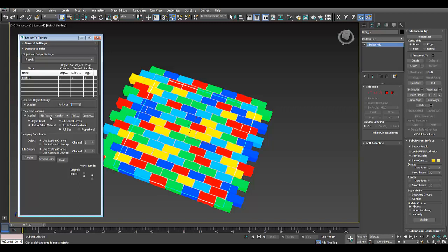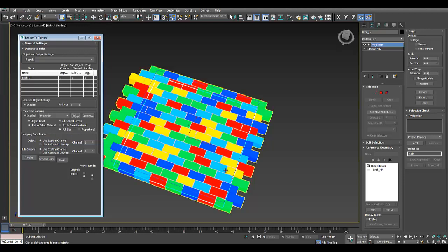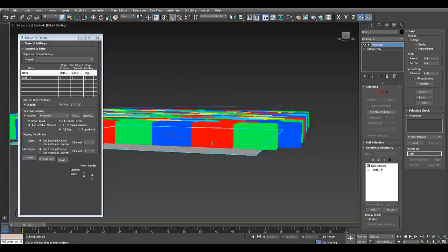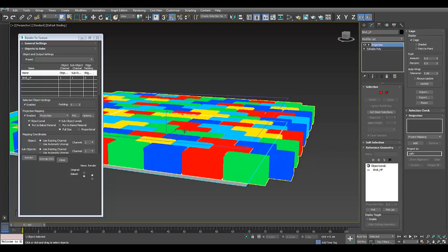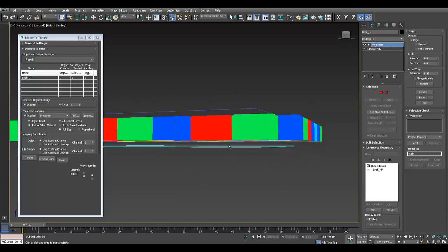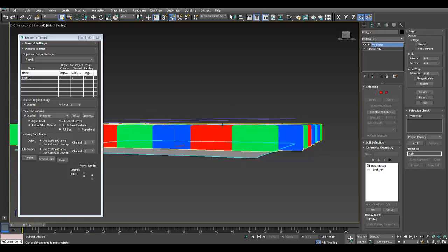So that's okay. Next thing I do is go into projection mapping, because we need to select what we actually want to bake. So this is our brick high poly. So I'm going to select that. What it's done is create what's called a cage, and what this tells 3ds Max to do is from the plane to that cage, we want you to bake what's in between there.